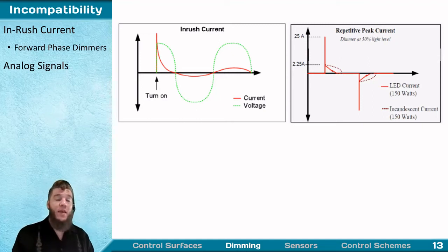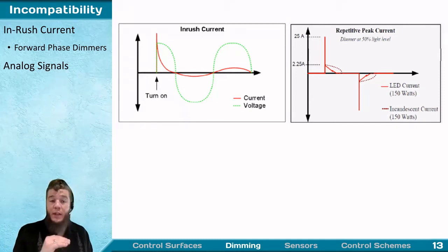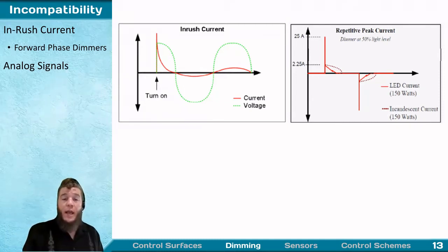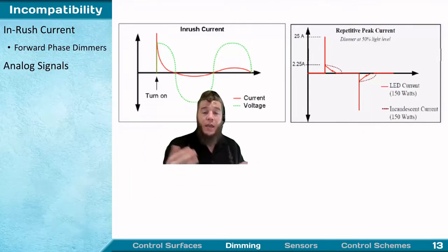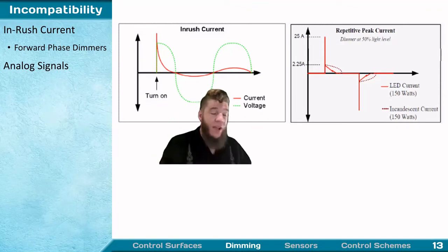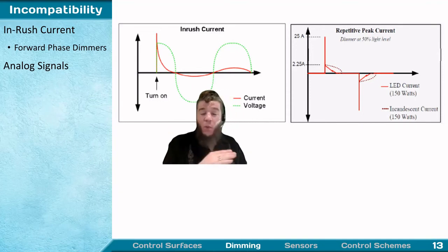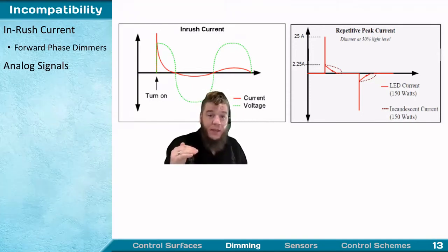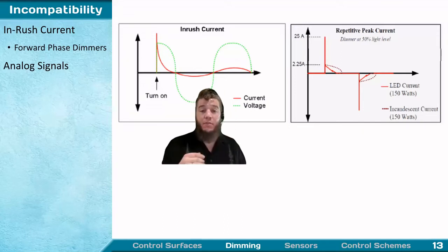What that means is that every time you use analog dimming to get a lower light output, instead of getting a lower light output directly, like you might from an incandescent source, what you're doing is you're just screwing up the power supply to the LED, and the driver has to figure out what that signal is supposed to mean, clean up the power that you just screwed up, and then try to give you some kind of meaningful feedback.